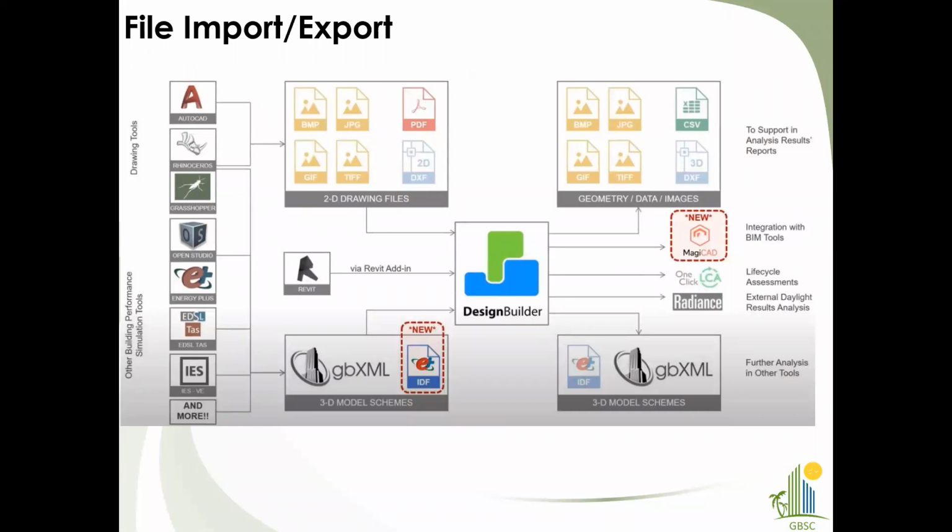So for the geometry part, we don't have to spend much time on the modeling front. Similarly, if we have a PDF file and don't have a CAD file, we can import the PDF file, scale it down, and then export the geometry. We can even import CAD files, image files, and files from Rhinoceros using GBXML format. These are the input interfaces which DesignBuilder supports, and as an output we can export DesignBuilder outputs into multiple software.